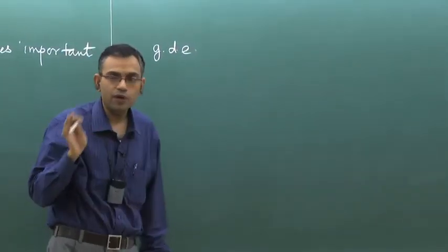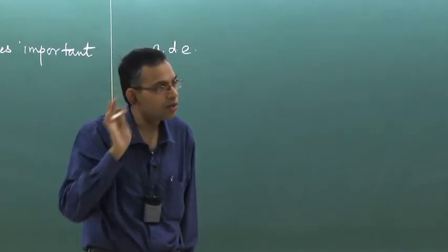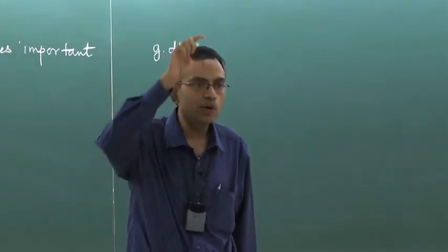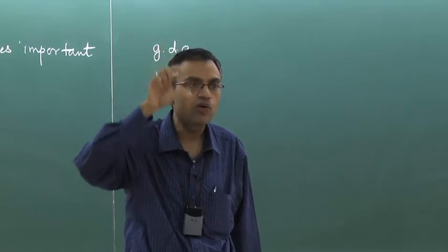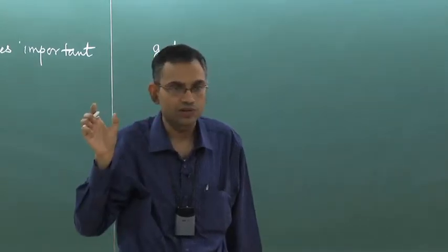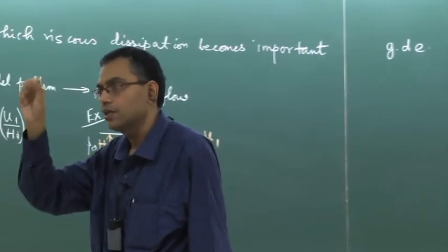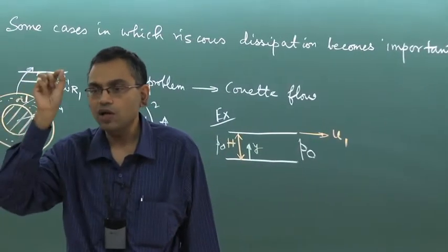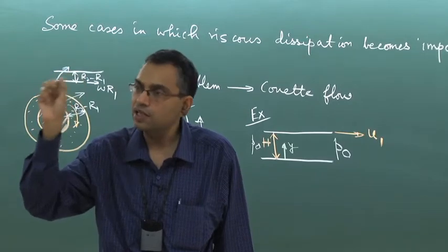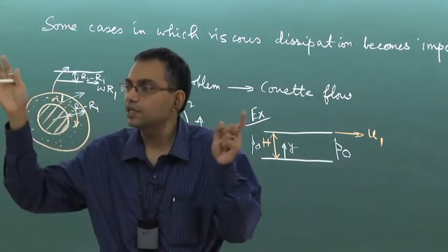So, if you recall, for fully developed flow del u del x equal to 0, and if there is no penetration at the wall, that is there are no holes at the wall, you have V equal to 0 also. So, left hand side u del u del x plus V del u del y, that term will be 0, and because of steady flow the unsteady term will also be 0. So, total acceleration is 0.